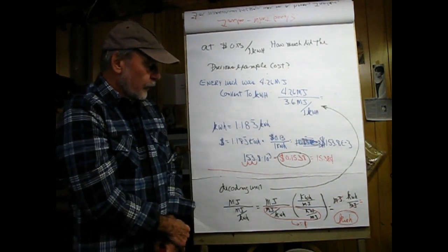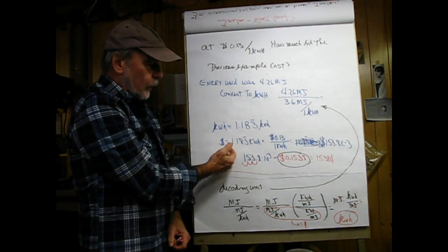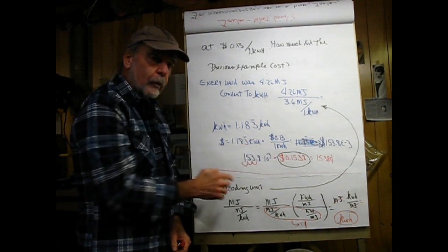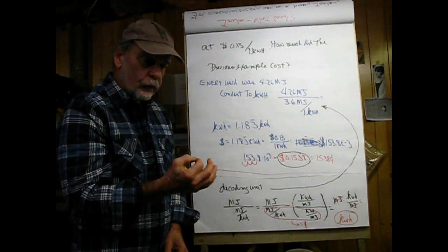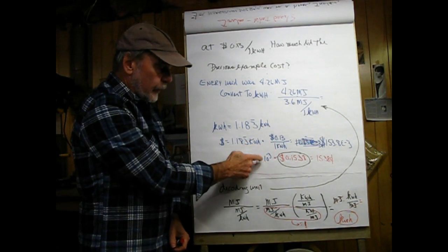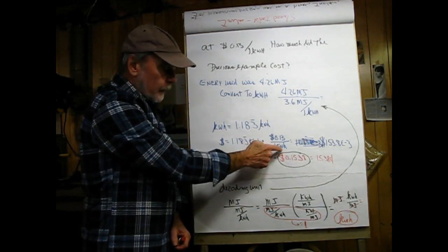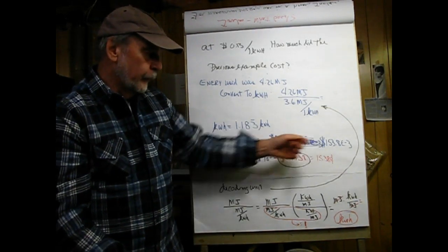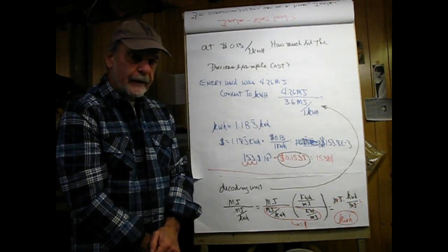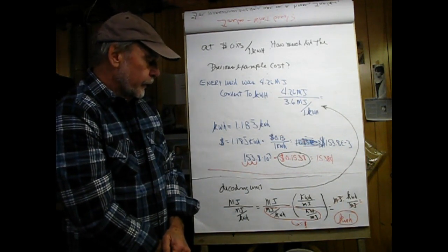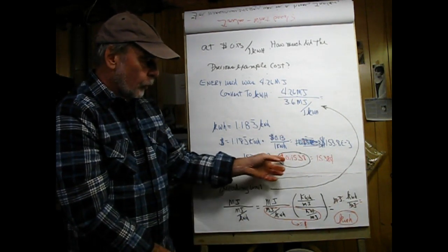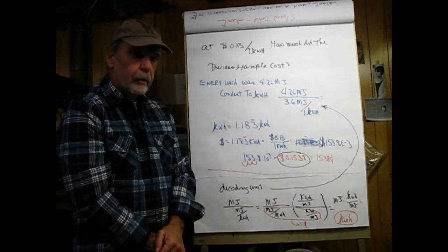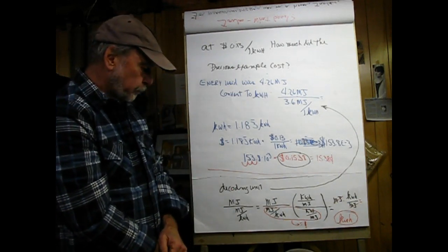Now, how much does it cost? Well, this is the amount we used in kilowatt hours, and it's 13 cents per kilowatt hour. And remember, I want the units to be in dollars. So when I arrange this equation, I know the kilowatt hours has to be in the denominator so they can divide out. In doing that, I end up on the calculator with 1.538 e to the negative 3. Then shifting the decimal point a little, we see that it costs 15.38 cents to use that much energy.